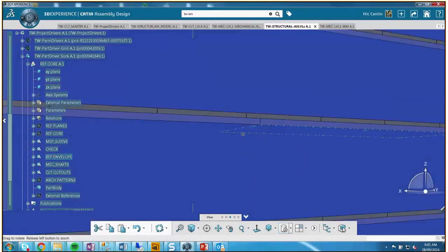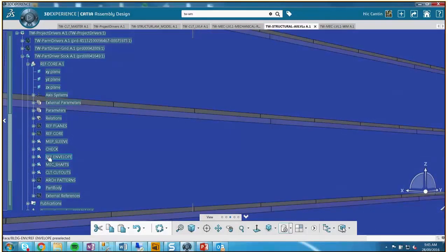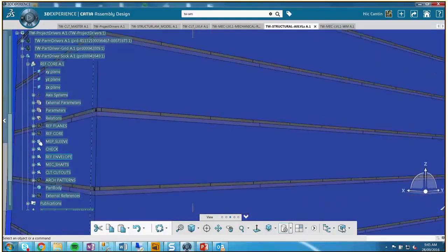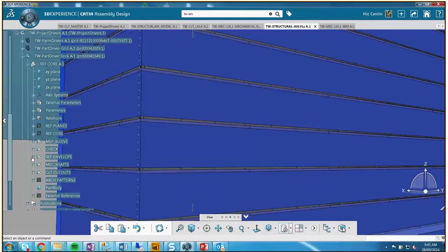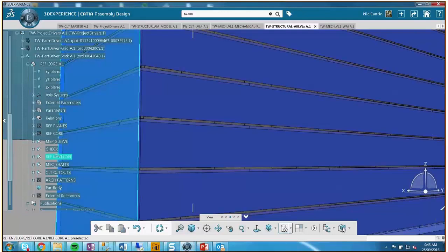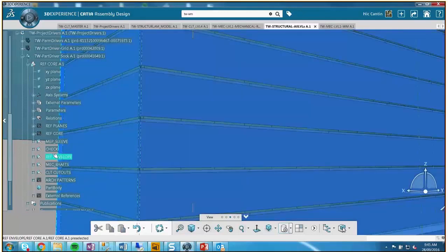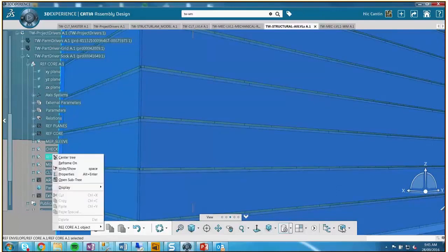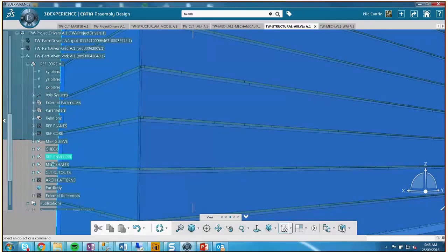But there's a tolerance on the top track that I think is a challenge if there's a slab above when you're installing. But I think that's the idea: we're going to try to learn from this and say, okay, how can we do the walls faster? Because the plumbing stacks that we showed, the prefab, they're flying it up at like 30% of the labor they used for a recent project that's basically the same size, but in concrete and was stick built. So there's been a lot of good learnings on the job for sure.